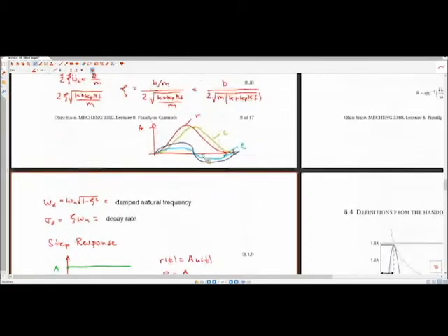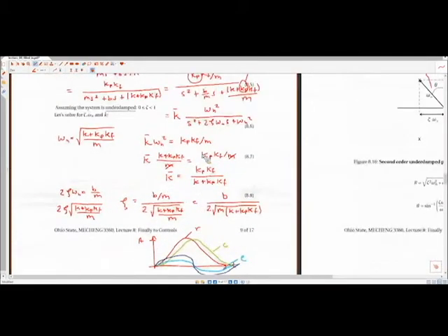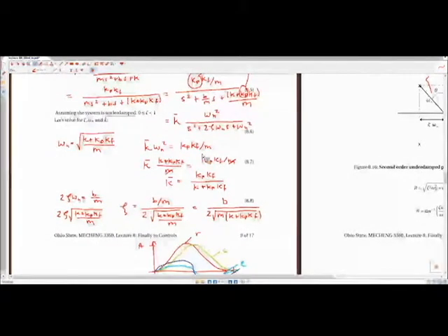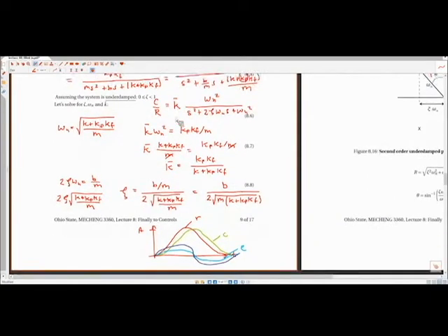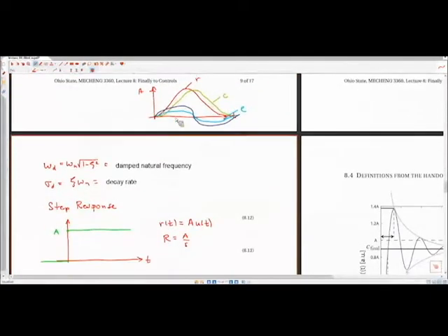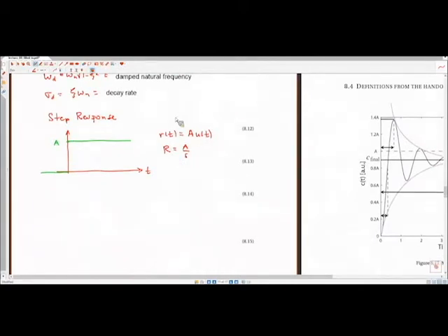So if we were to take the inverse Laplace transform of this by using the Laplace transform table that was important on homework 5, right? That was given on the quiz. We would get that C of t is equal to k bar A times 1 minus e to the negative sigma d t.